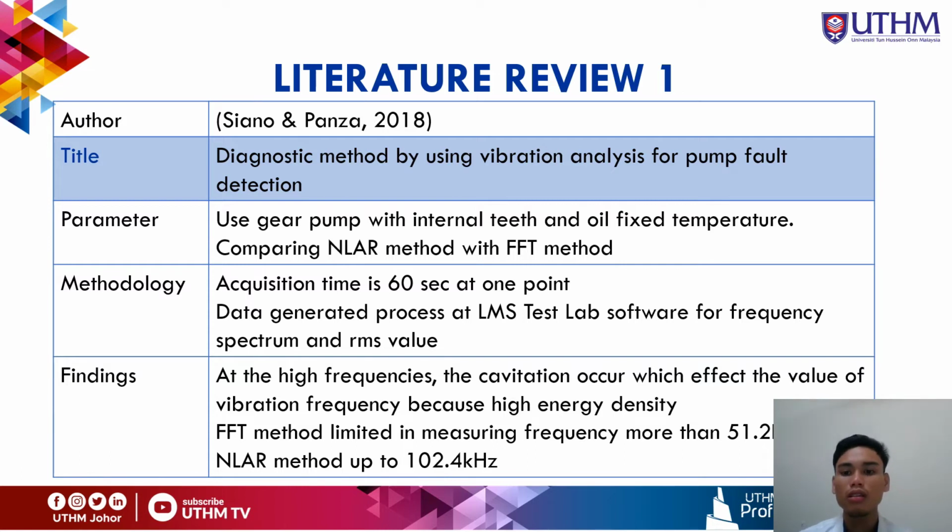For the literature review on the previous research, first of all, the title is Diagnostic Method Using Vibration Analysis for Pump Fault Detection by Ciano and Panza in 2018. This research found that at higher frequency, cavitation occurs, which affects the value of vibration frequency because of the high energy density.